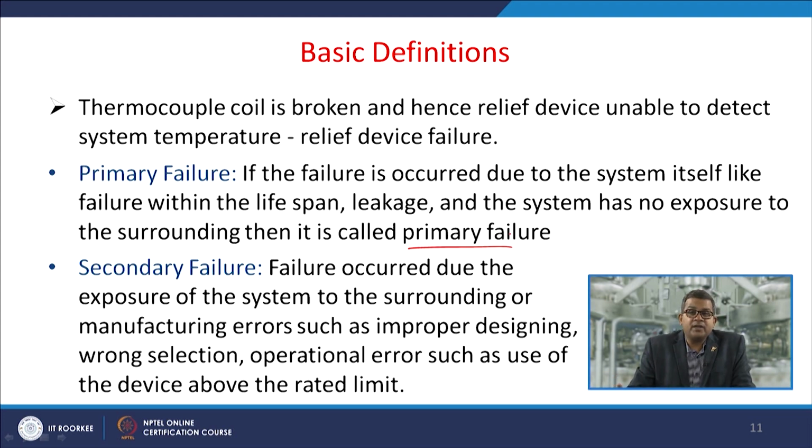Now the secondary failure is the failure occurring due to the exposure of the system to the surroundings or manufacturing errors, such as improper design, which may lead to such kind of failure, or wrong selection, either in terms of raw material or in terms of process conditions, like with respect to pressure and temperature. Sometimes there may be certain operational errors, such as the use of a device above the rated limit, etc. So these are termed as the secondary failure.